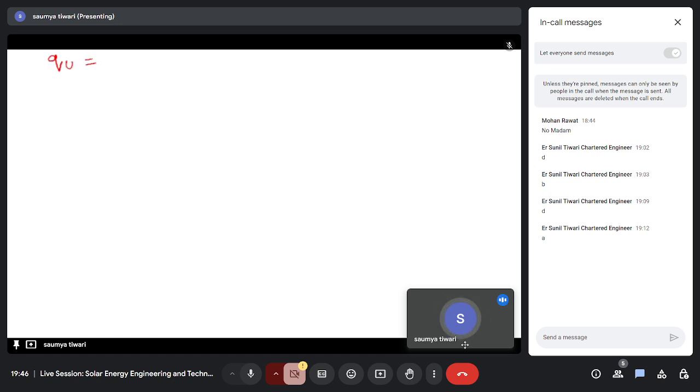So Q useful you can write as FR into (W minus D naught) into L into (S minus overall heat loss coefficient upon concentration ratio into (fluid inlet temperature minus your ambient temperature)). So in terms of FR and fluid inlet temperature, you can write Q useful as the shown formula.